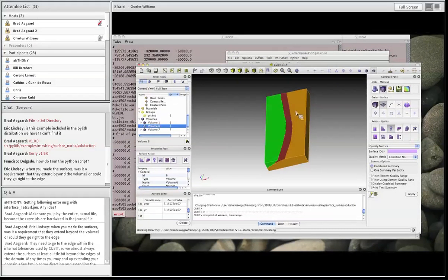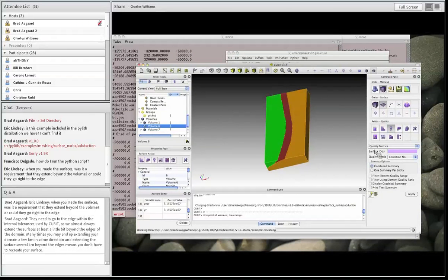you'll notice that this is not a true problem because in reality, we're going to want our boundaries for this mesh far away from where things are going on, which is along the faults here. So that for a real problem, what you would typically do is have this volume contained within a larger volume so that you could have a mesh that extended much further out from here. And you would embed this volume within the larger volume. So it's a toy problem, but it's not particularly realistic.